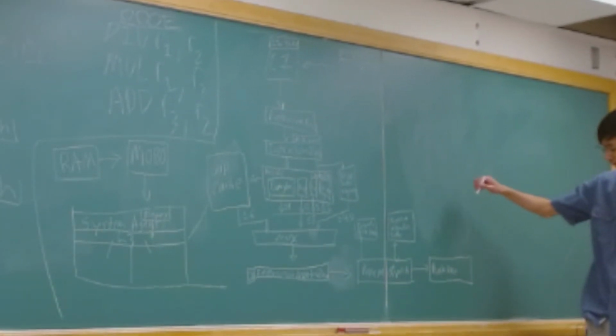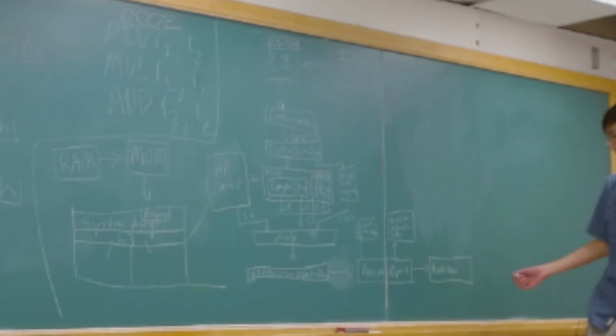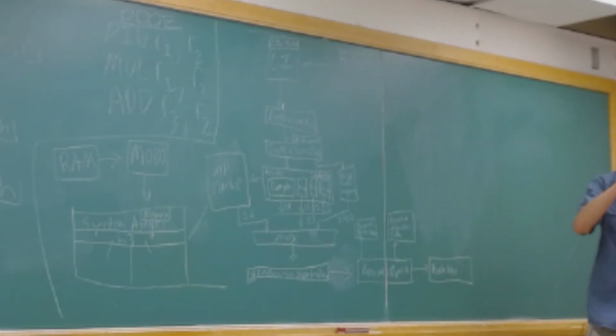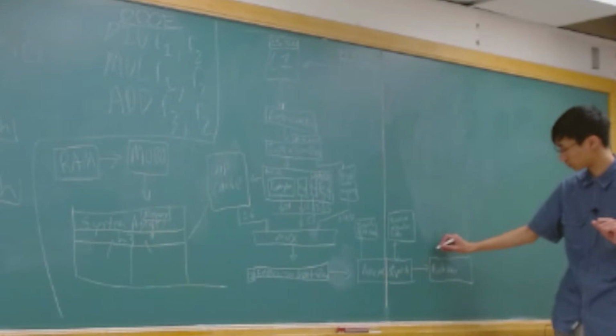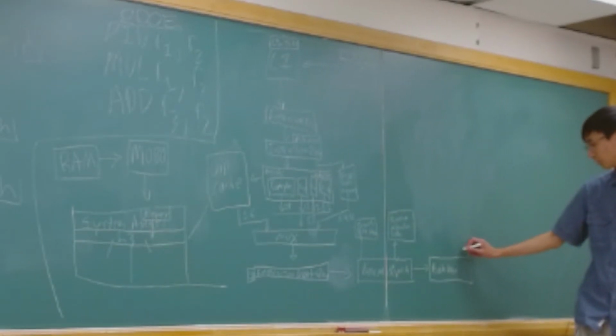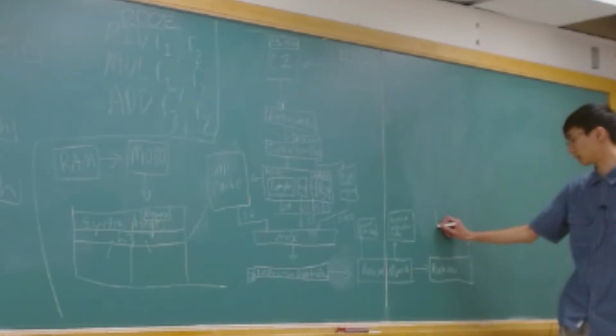The reorder buffer has 224 entries in the Skylake, and it will also help the rename dispatch system to keep track of everything, right? It's part of that Tomasulo algorithm. The reorder buffer will push instructions into the out of order execution resources.